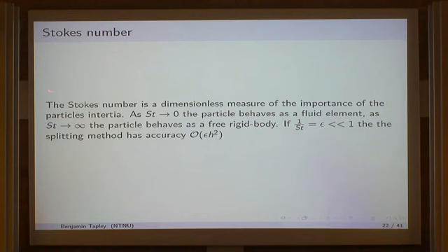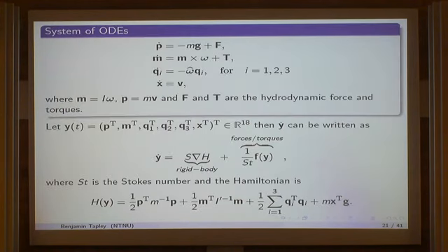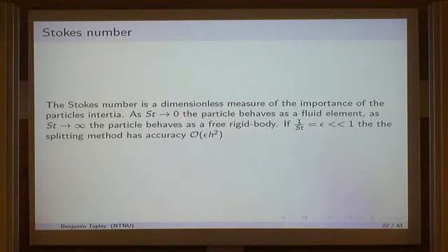Oh, not yet. So basically, here we have this 1 over St, where St is the Stokes number, and that basically determines the magnitude of this force. That's going to be important later when we consider the splitting method. So as the Stokes number goes to 0, the particle behaves as if it was a fluid element and moves exactly along the streamlines of the fluid. But as the Stokes number goes to infinity, the particle behaves as a free rigid body, as if it was moving through a vacuum.